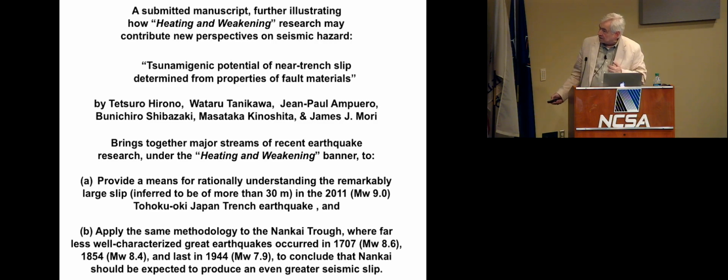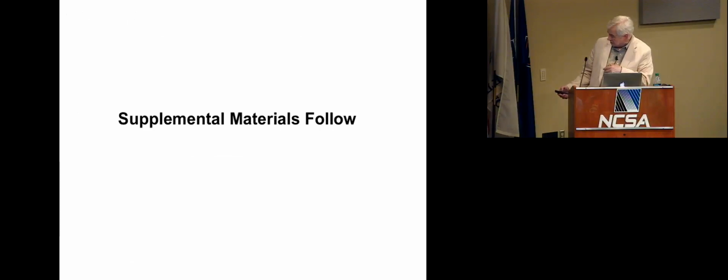And the way they go about making the argument is they use borings into the seafloor to try to get frictional and poromechanical properties of sediments and ask, could the stuff in the south be susceptible to a thermal pressurization weakening, and hence would it have the potential to let a little earthquake, once started, run away and become large? And at least that's their scenario. It's all a hypothesis at this point, but it's their scenario, and using concepts like I've been going over today as a background for assessing seismic risk.